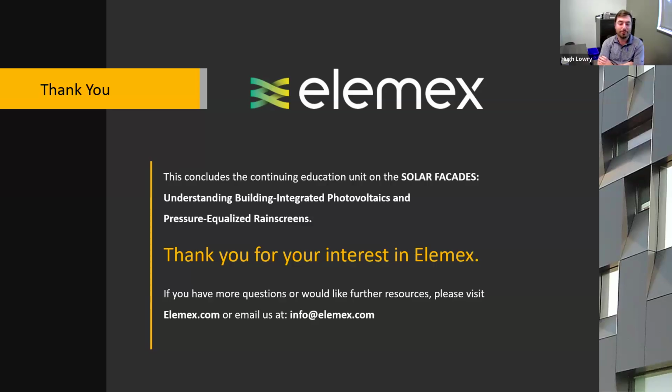So it actually has to do with the cell arrangement. So typically the solar cells themselves, I wish I had one. Actually, I do have one on my desk. Look at that. Typically the solar cells themselves are about 4 to 6 inches by 4 to 6 inches wide. So those sizes that I mentioned before fit in well with either a 60 or 72 cell panel, and those are just basically neat sizes, a neat amount of cells that fit together electrically. So those are basically why those two standard sizes are chosen.